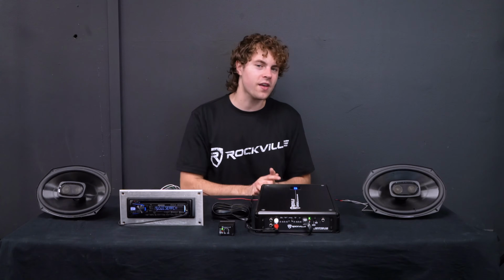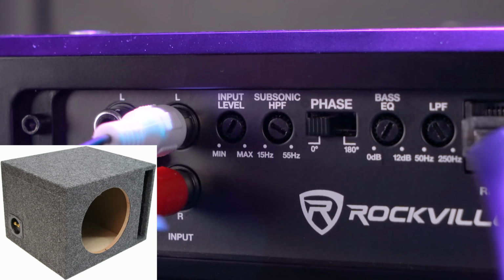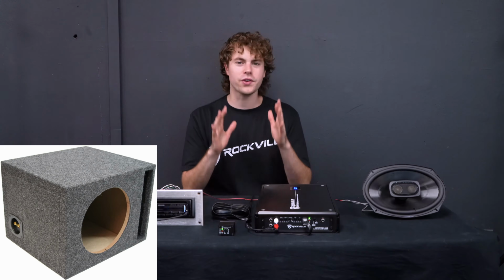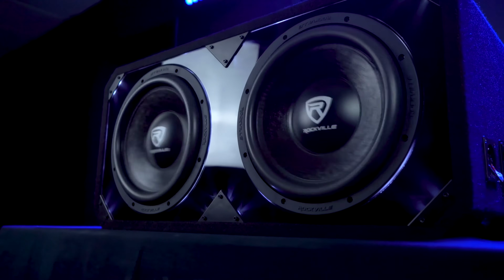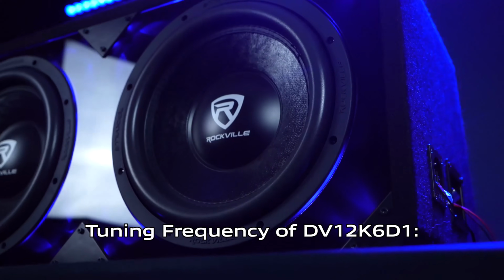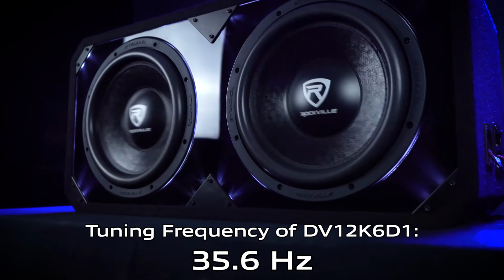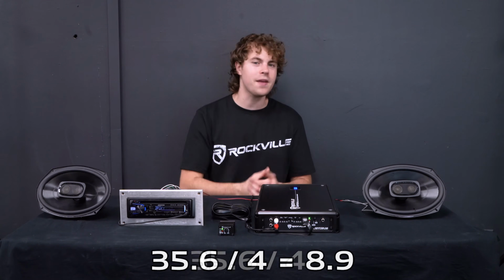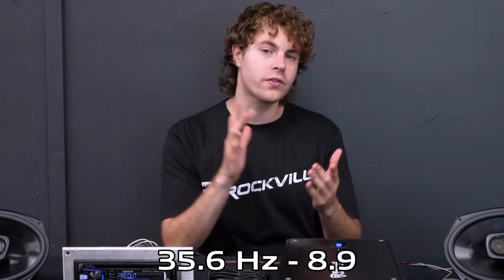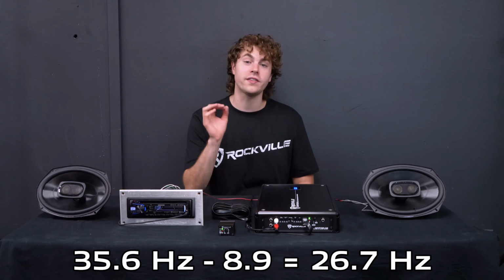When setting the subsonic filter for your vented enclosure, you're going to want to set it an octave below the tuning frequency of that enclosure. You can always find out the tuning frequency of your enclosure through the owner's manual or the manufacturer's specification. So for example, the tuning frequency of our subwoofer, the DB12K61, is 35.6 Hertz. Now you're going to want to take that number and divide it by 4, which equals out to 8.9. Then you subtract that from our tuning frequency of 35.6, which equals out to 26.7 Hertz.